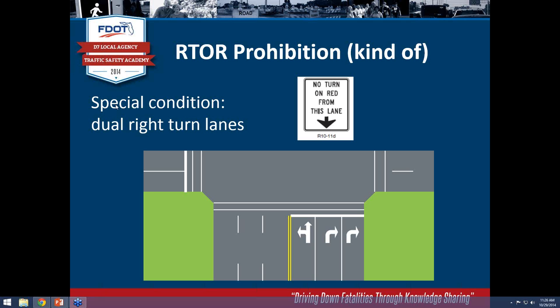Something that municipalities do as well, when the signal would have gone to flash, is greatly reduce the cycle length, so that from the side street you're not sitting there waiting for 2 minutes for the signal to come back around. Yeah, if that's kind of a concern. Because you've got traffic signals at 6-lane divided highways, and it's just kind of dangerous to make a direct left without the signal assigning right away.